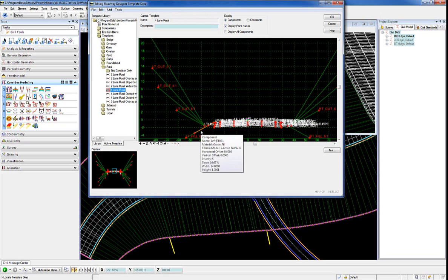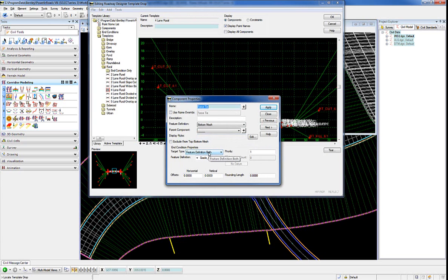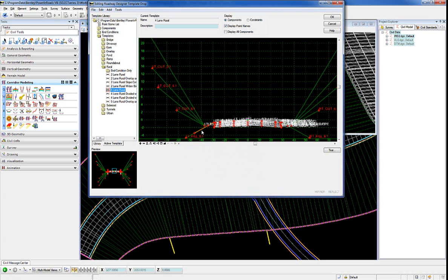I have a priority 1 in condition here. Before we go to drop the 6-to-1 slope there, priority 1 is going to be looking for this feature definition. And I have the method set to both, so that both corridors will target the X, Y, and the Z of that line I drew, and so there won't be any overlap, and they'll match up exactly at that. And the feature definition they're looking for is the fixed grade tie there. I have that set to priority 1, so if that exists, it's going to find it. If it fails, it's going to go and place the end conditions there.